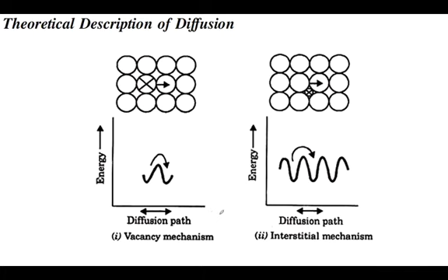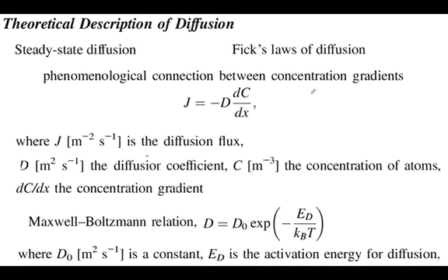Now you can have an already created vacancy where there is no atom, so this dopant atom can take the place of a particular vacancy, or it can sit somewhere in between. Remember that this position is not part of the crystal. Wherever you have empty space in the unit cell, it can sit. That is sort of an interstitial position. It occupies the interstitial position. So this is the diffusion mechanism that happens inside the solid.